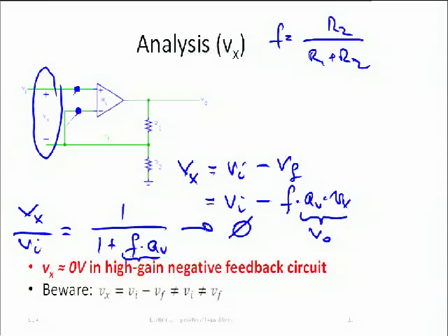Now, in some cases, when we build an extremely high precision circuit, maybe it matters. But most of the time, this 1 microvolt is as good as 0. And consequently, if we assume that our operational amplifier is ideal, then we can also assume that Vx is 0, and our calculations get a lot easier. And that's what we're going to see now.